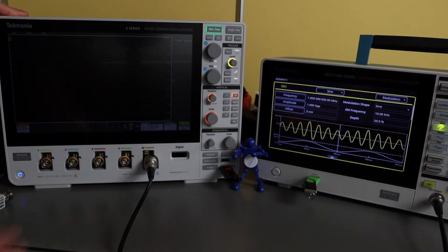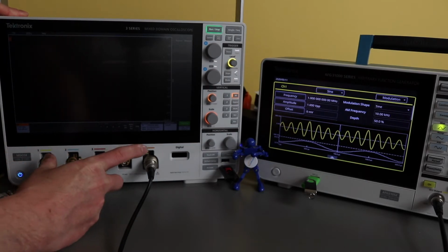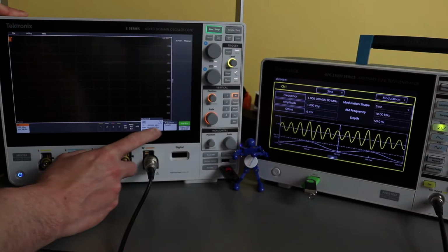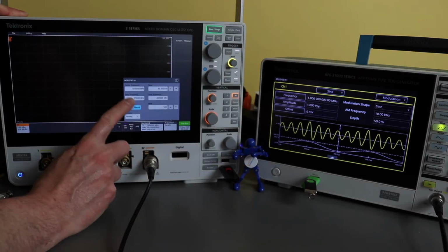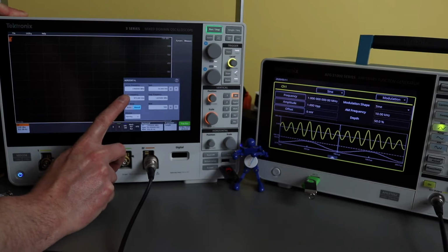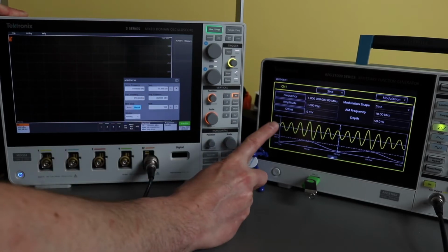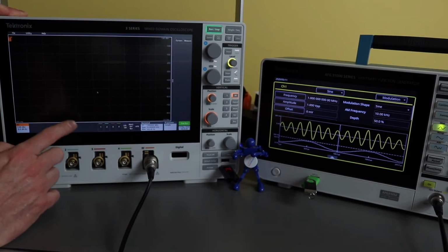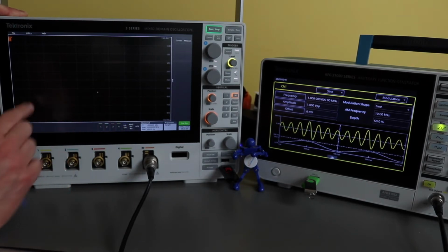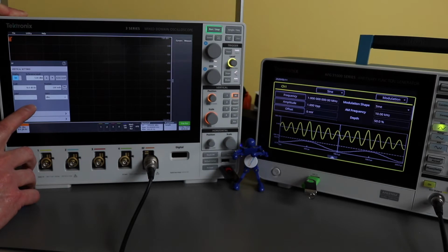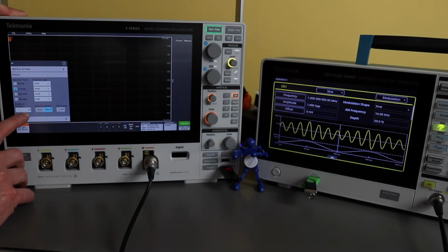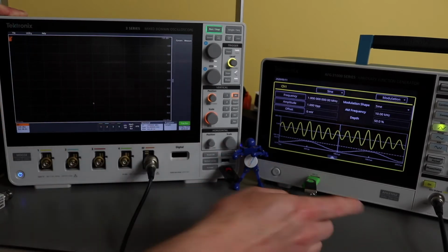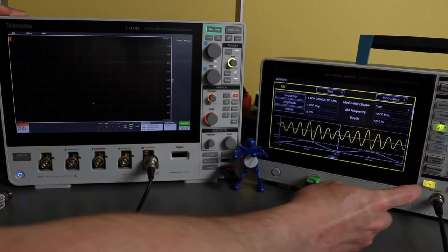Now the spectrum analyzer, unlike all the other tests where I'd set this up for a wide span, is now set up for a very narrow span, and the center frequency has been set to match the frequency of my carrier waveform. And the other aspect that I've done for this is to set this up to quite a high level of averages to increase the accuracy of this measurement. So we'll put our output on,